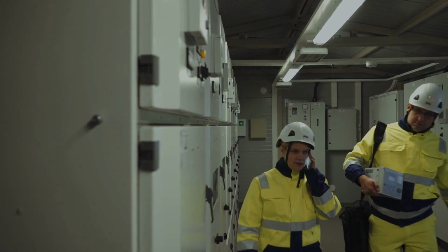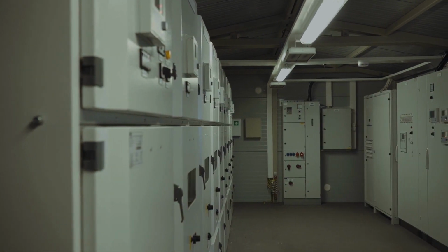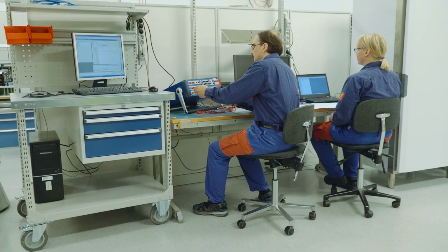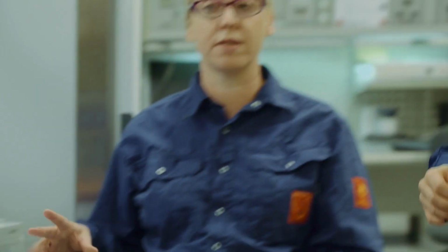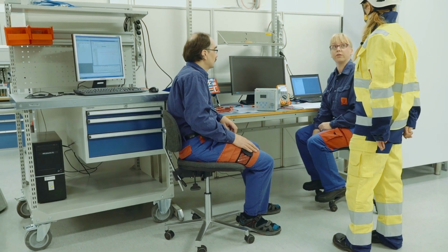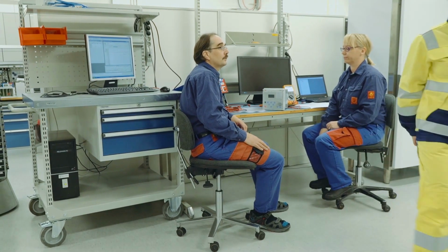When the power has been safely restored, the collected data can be further investigated to analyze the situation fully. The replaced relay can be tested and the disturbance recorder data used for simulation of the fault situation. We will continue on this a bit later, but first, let's take a closer look at the Relion 611 series.